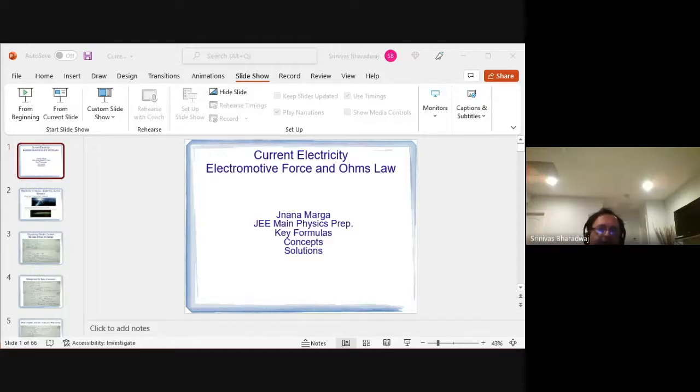Now, if you apply a voltage across this of 5 root 2, what is the current? 5 root 2 by 10. So 5 root 2 by 10 is the current. I square times 4, I square R, right? I was calculating the total power, but you don't need the total power. So I square times 4. I is 5 root 2 divided by 10.